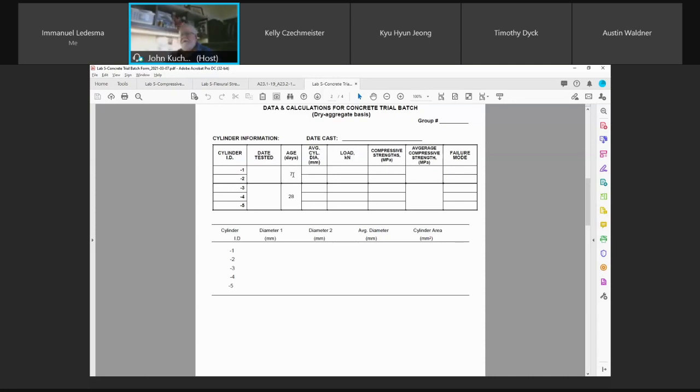Now, if you had 2 7-days, same batch of concrete. One broke at 22, one broke at 29, 30. If it made 30, there's no reason why the other one shouldn't. Now you can safely say, yeah, I think my strength at 28 days is okay.